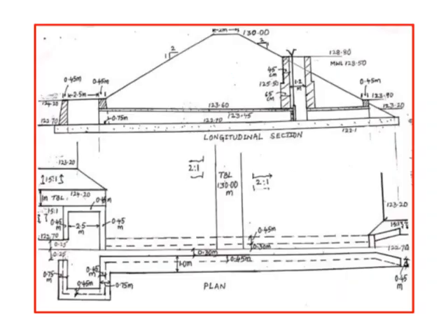So this is the drawing part pertaining to the design sheet. I told you that this is the regulating arrangement. A person can come over here and simply regulate, and this is the diaphragm wall that you have provided. There is a 45 centimeter opening, and then the shutter gates are provided, which are regulated here. A person can come here, simply lift it, and then the water enters here.